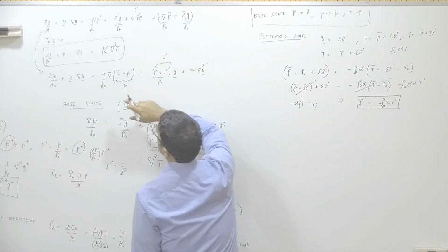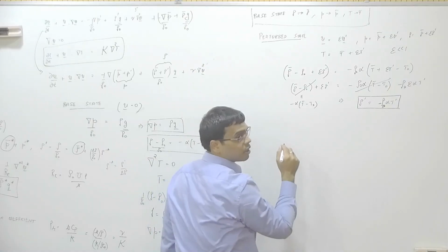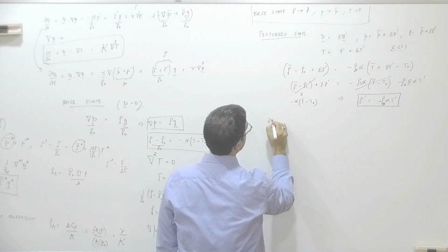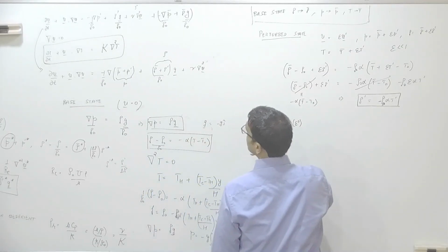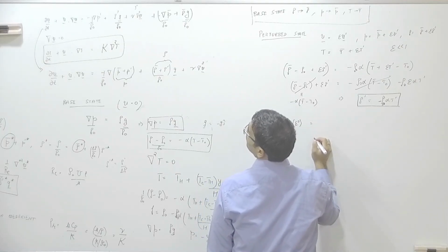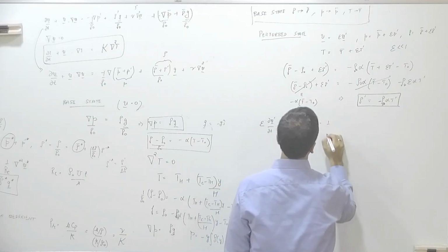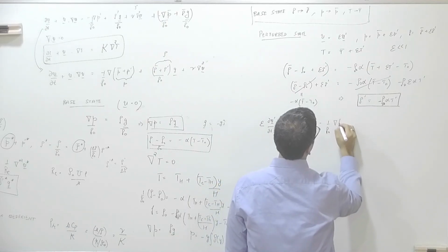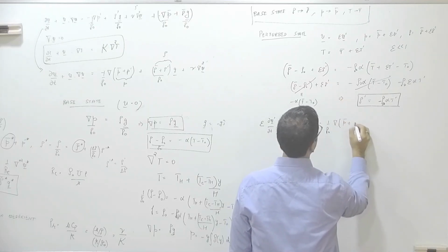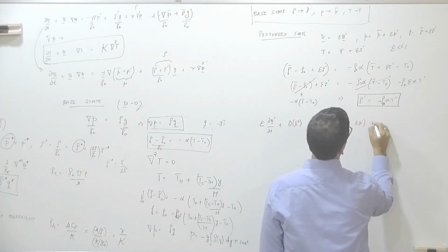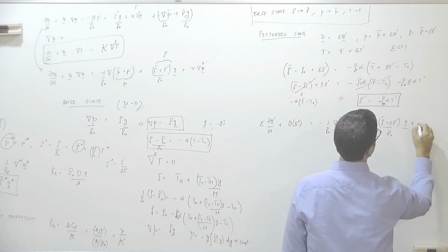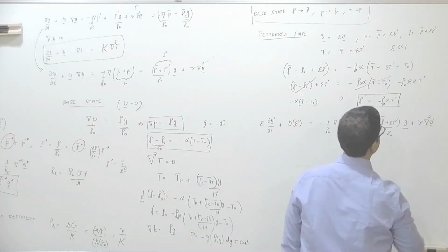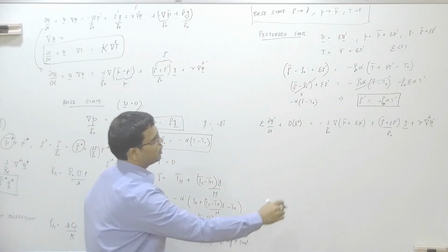Okay, now once we have this, the perturbed state density, let us substitute this velocity in our momentum equation, and we will retain order epsilon terms only. Okay, so we will ignore any higher order terms. So you have del u prime by del t plus order epsilon square term. So let me write epsilon here also, equals, what do we have? Minus 1 by rho naught grad of p bar plus epsilon p prime, and then we have a plus rho bar plus epsilon rho prime over rho naught, this whole times g plus nu del square u prime. Okay, and there is an epsilon here.